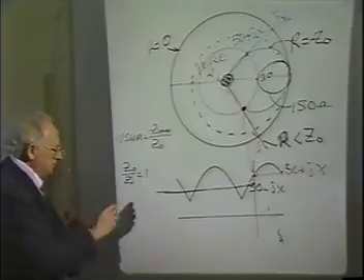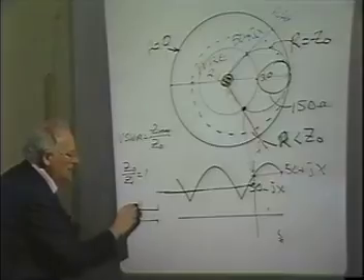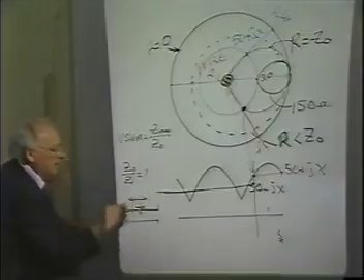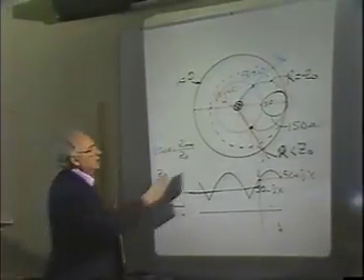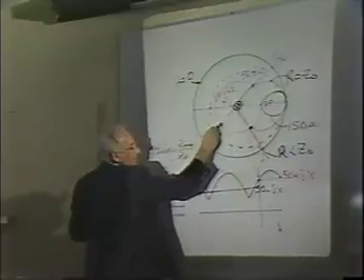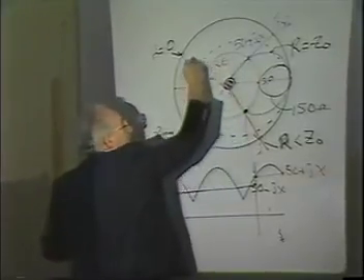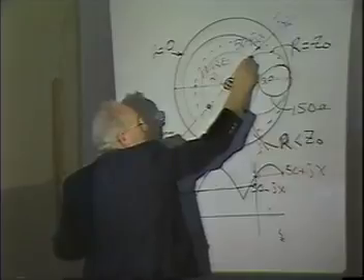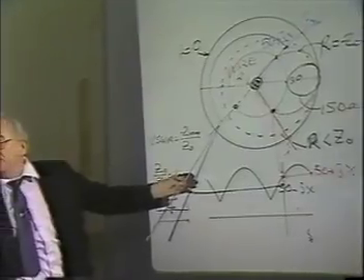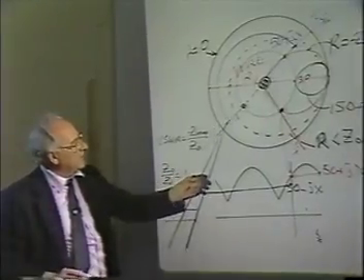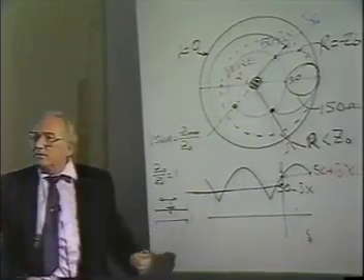Look at this in terms of a slide screw tuner. A slide screw tuner is a waveguide device that has a metal probe that can go down in the guide like this, but it can be moved in either direction. Now notice, this is a shunt problem, right? In other words, looking at this like this, this really is this point over here. Now I travel along this transmission line until I get over to here, around to this point here, which is how far I would have to travel. In this case, it's exactly 180 degrees, isn't it? Just so happens that I chose it that way. So after I go around 180 degrees at this point here, then I can match the transmission line.